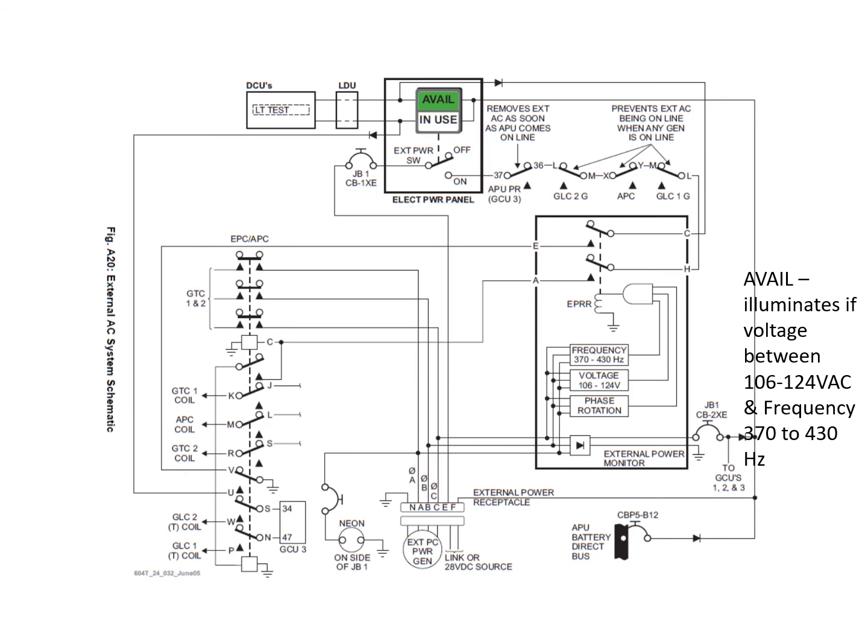It's coming out of pin L there, coming down into H, into the external power monitor, to the EPRR. If the EPRR is energized, because the EPM is happy with all the quality, then the power is allowed to get routed down, and it goes down to the external power contactor, boom, boom, boom, and the external power can now come online.